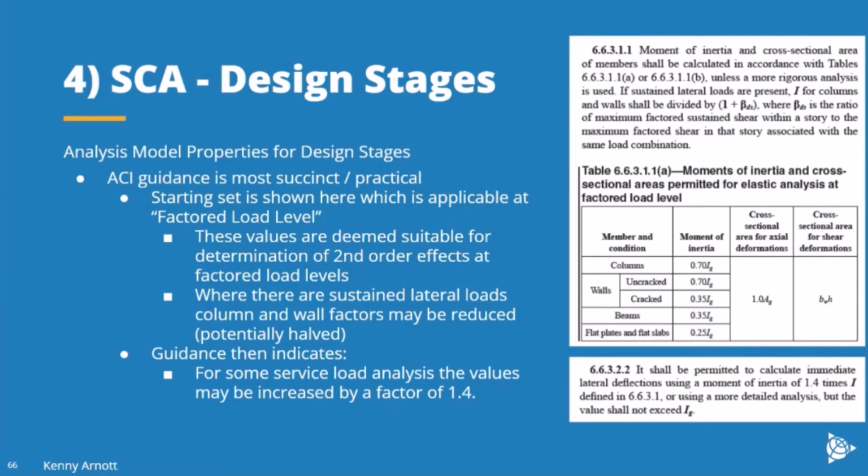So if you have sustained lateral loading, there's a further adjustment to make. It also talks about a clause, shown here, that this is for the ultimate limit state. If you're dealing with a serviceability condition, then you can increase these factors, so make less of a reduction to the properties, with an increased factor of 1.4.